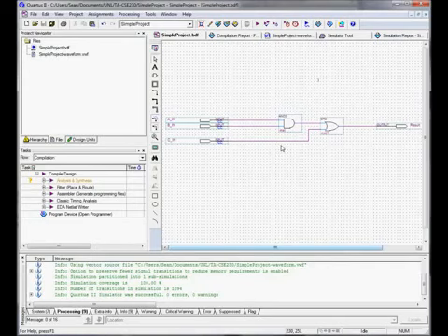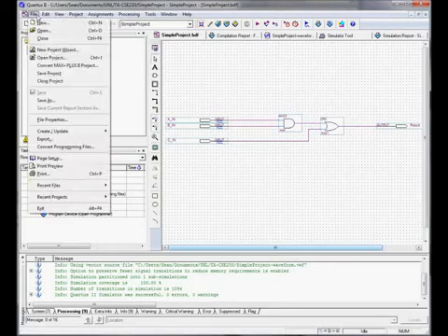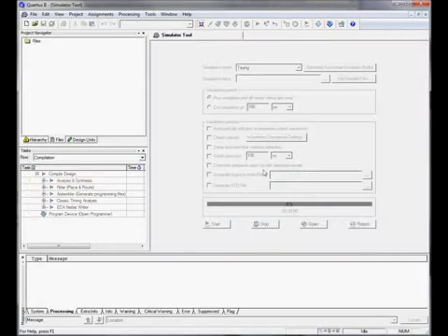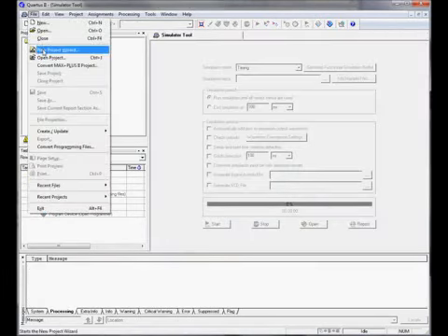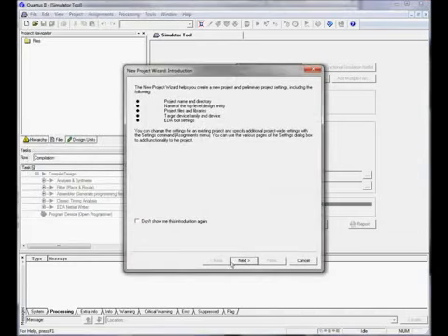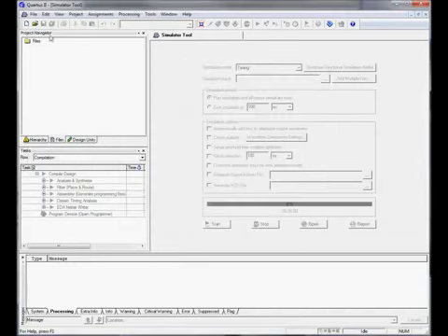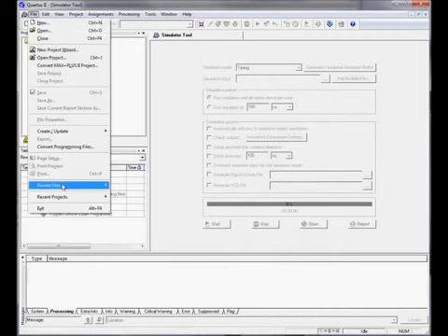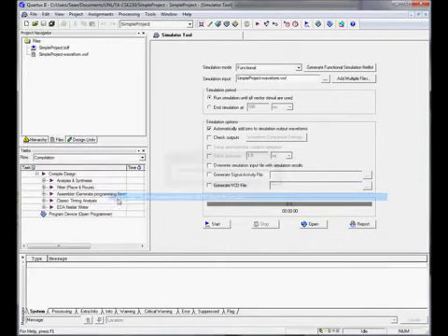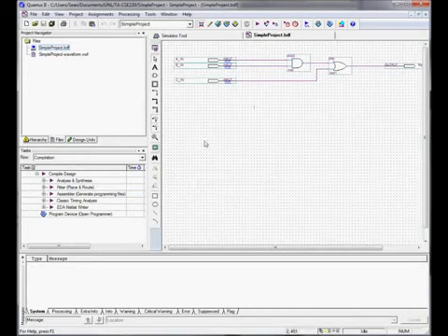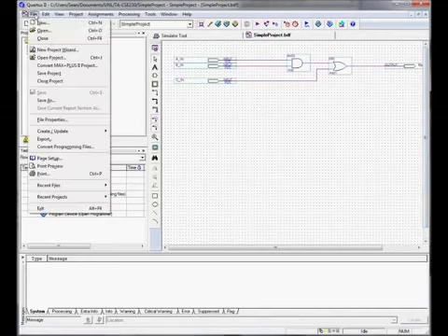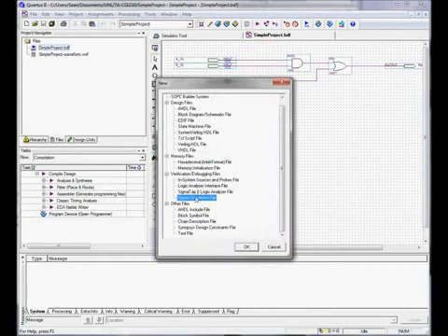So I'm going to close this project and we're going to open a new one. Actually, I'm going to scratch that. I'm going to reopen that project because we can do it right in here. So let's implement this entire function here as a single VHDL file. It'll save us some time. We're going to go to New. We're going to go to VHDL file here. That's underneath Design Files, once again, just like our block diagram was.